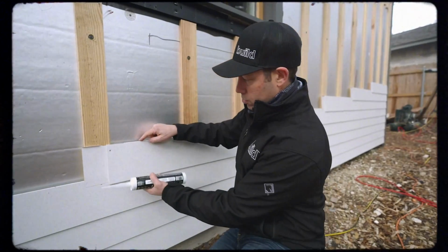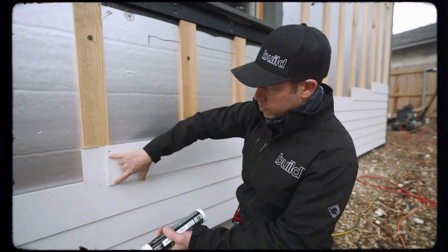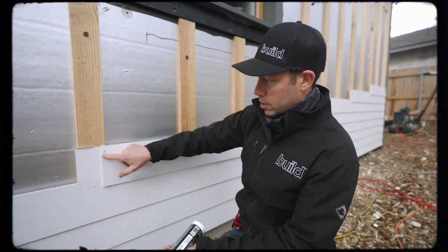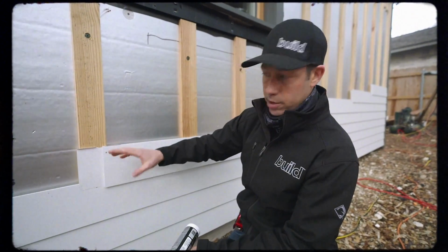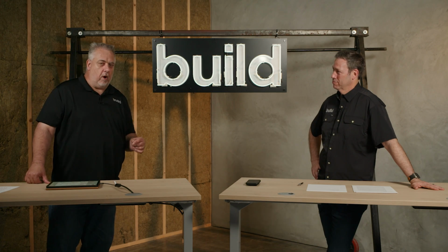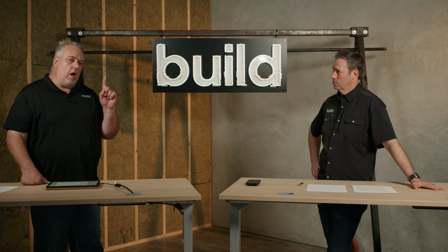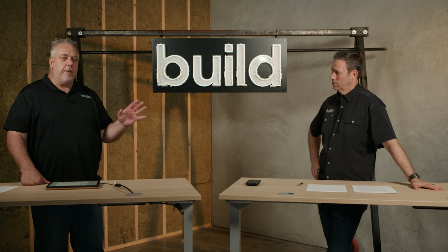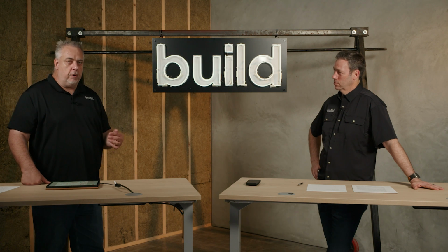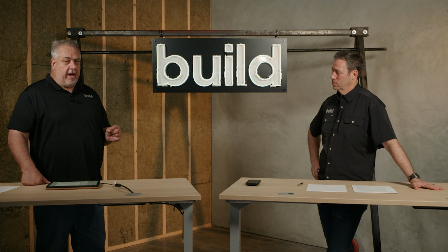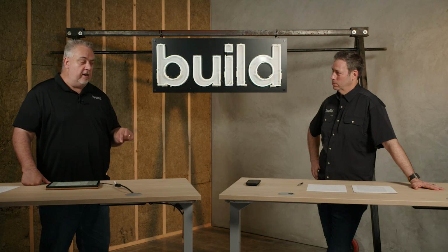Now, a lot of you are going to say, well, nothing's getting back there, Steve. We seal it up really good. I mean, Jimmy the builder went through 3 cases of sealant on my house. Here's what I know about building science, and this is 30 years, it's only a sample of one. The minute you break out a caulking gun, a roll of tape, or some type of adhesive closure membrane, the very first question you should be asking is, what am I sealing in, not out?